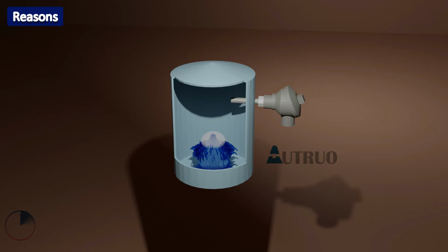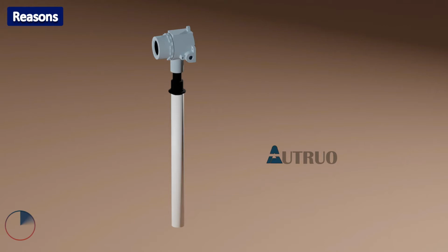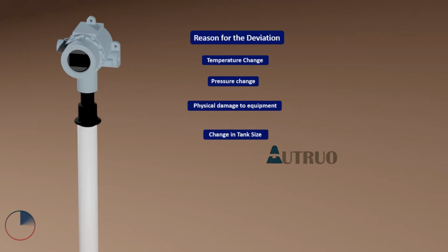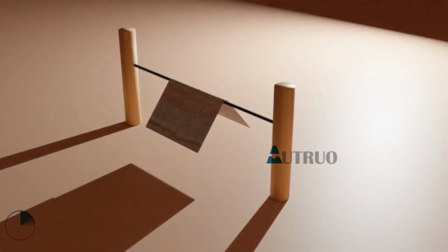This error in ratio measurement can be due to temperature change, pressure, physical damage to the sensing diaphragm and changes in the ambient conditions. Sudden changes made to the vessels can also affect the instrument's readings. To fully understand these effects, let's look at a typical real-life example.